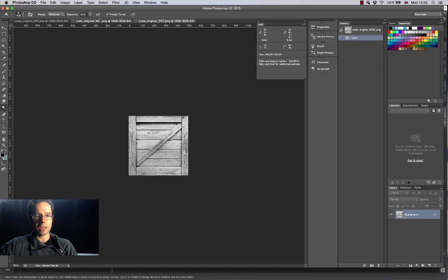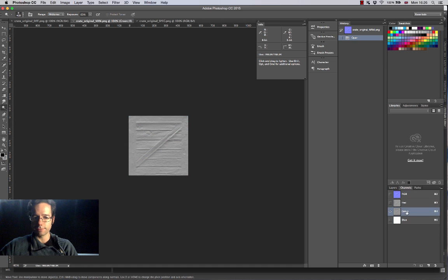And then I've generated a third image, which is a normal image over here. This is created with a piece of software called Crazy Bump, which is free and available for people who have a Macintosh. But effectively, if it had a black and white version of it, it would be kind of like the pattern of the surface roughness of the actual object over here. So again, I'm going to leave this on its normal display over here. But those three images alongside with Arnold are going to help me make my crate look a little bit more believable.